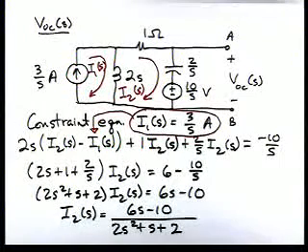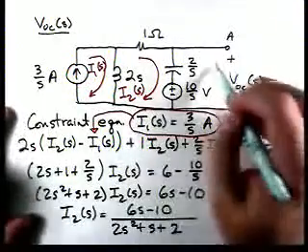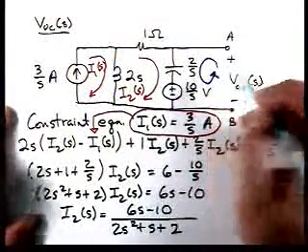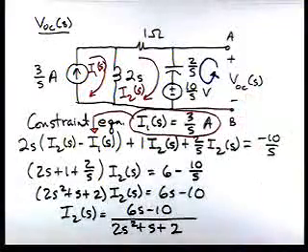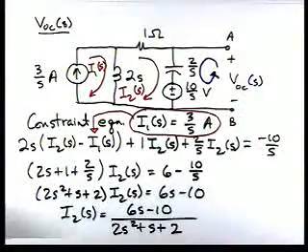Now that's all we need to be able to solve for VOC, because we can now apply KVL to that loop to get an expression for VOC.